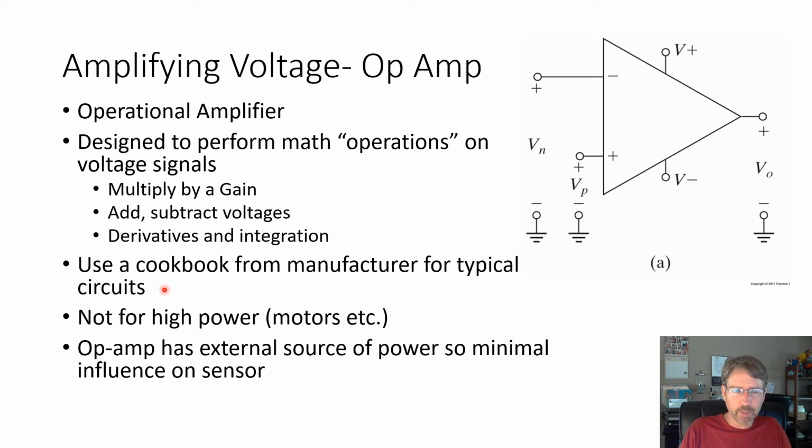Normally, you look for an op amp cookbook. There are books that are titled that. Manufacturers will have common circuit designs. So you don't normally have to design something for an op amp. If you know what math you want to do, you can look it up.